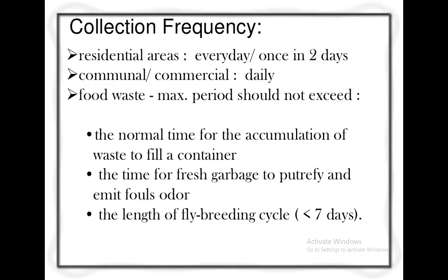So the collection frequency in residential areas may be every day or once in 2 days. The waste is collected from residential areas, and every day the waste is collected by waste carrying vehicles from commercial buildings in the commercial areas. The frequency of collection is daily. Waste is collected day by day.